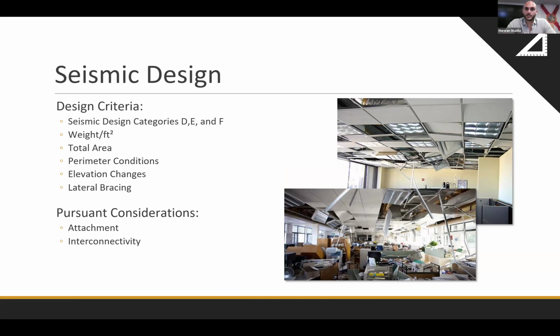With regard to seismic design, it's a very, very lightweight system, as I mentioned, being 1.6 pounds a square foot. We've installed on the West Coast, accommodating some of these seismic design categories, D, E, and F, with attaching the system to a heavy duty grid system or direct attaching, just depending on the local code. If you have any questions on that, we'd be happy to speak with you and find a solution for the application and the project that you're working on.